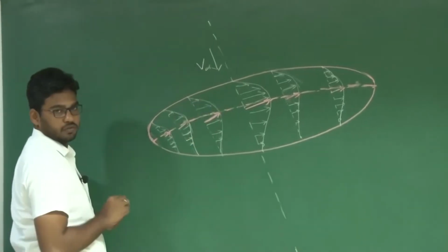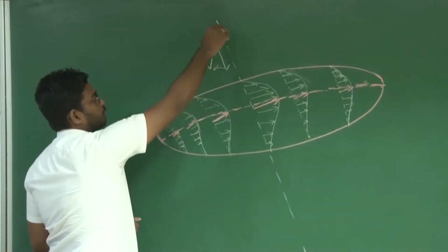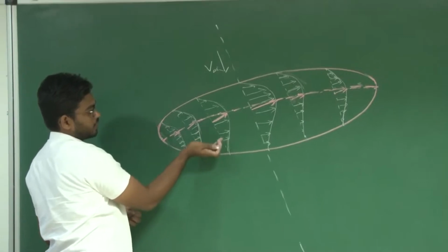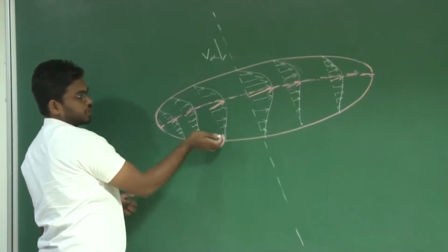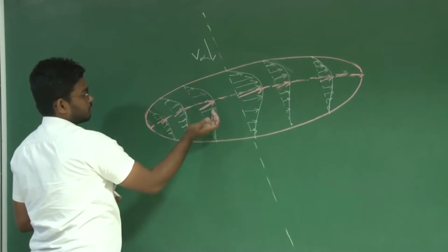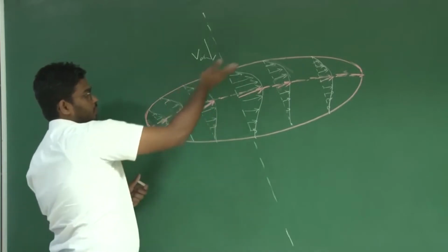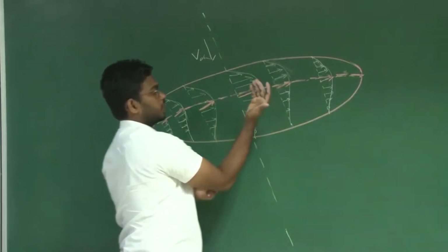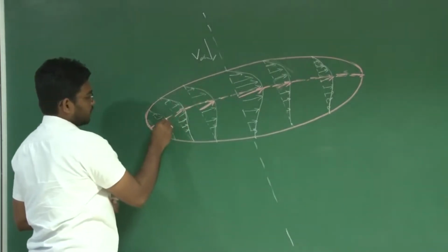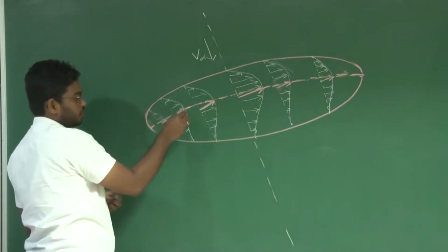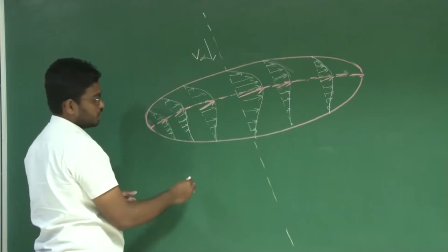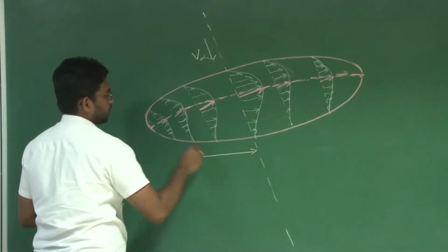Consider an enlarged view of that elliptic wing. Let us say the flow is along this, parallel to this fuselage reference line. So the white lines, or the arrows here, represent the pressure distribution at each and every location of this elliptic wing. Now this pressure distribution is perpendicular to this planform, coming out of the surface of this blackboard. Now we can get a resultant force, and a component of that perpendicular to the free stream is the lift at that particular span location.